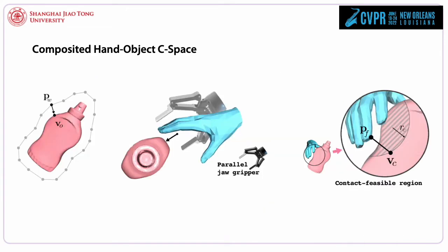For generating composite hand-object poses, we follow the conclusion from several previous methods that enforcing contact can help us optimize a cross grasp. We start from an existing grasp, mimicking the canonical grasping poses of a simple parallel gripper, and randomly move the wrist around the offset surface of the object. At each wrist location, we assign a contact-visible region on the object surface for each finger. Finally, we optimize the grasp by minimizing the displacement between the fingers and the contact regions.